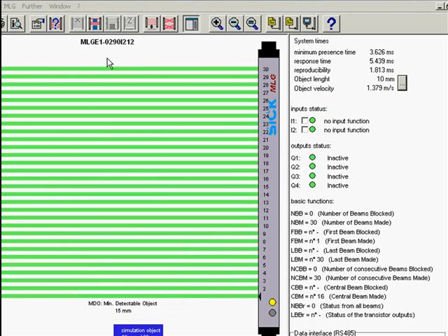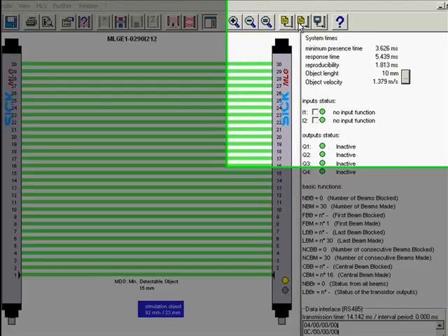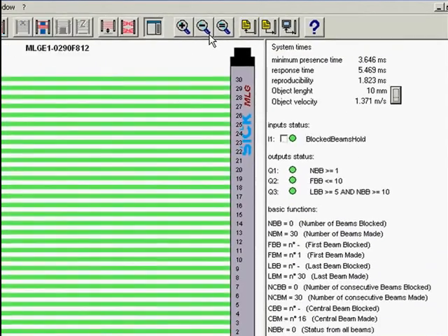So after making any configuration changes, using the multi-scan, changing what your outputs are, or your 485 output data is, you do need to upload this to these sensors. So you actually have to click the button that says, from the parameterization up to the light grid, and you do that uploading, and it will get all that information in. Then you can save it as well.